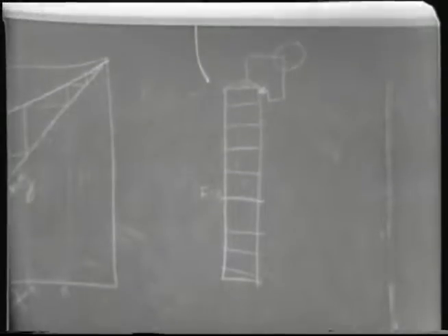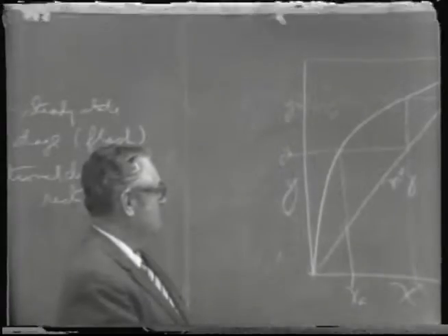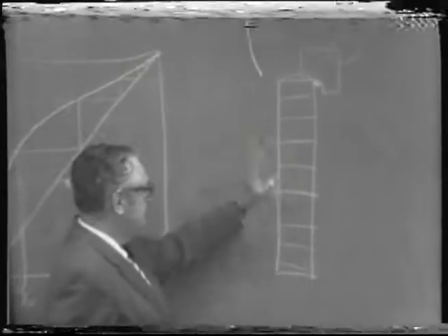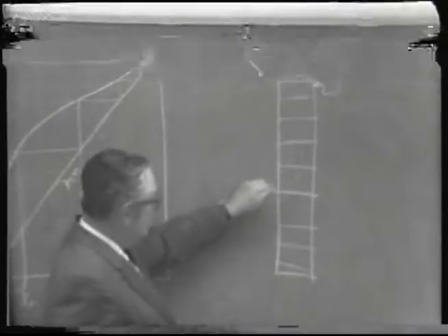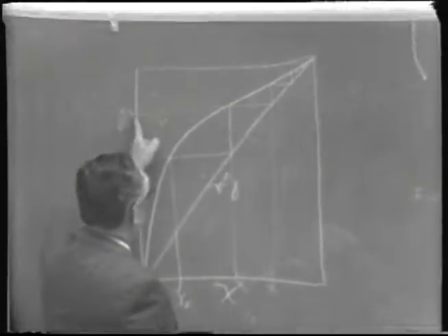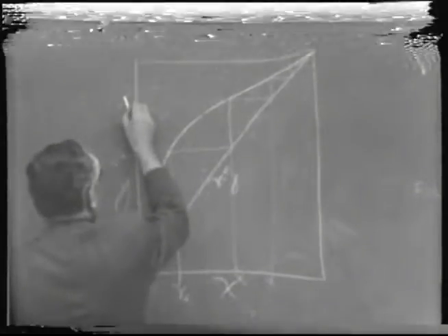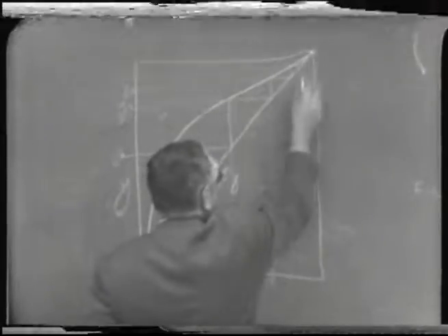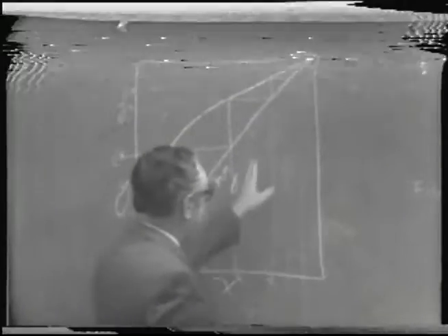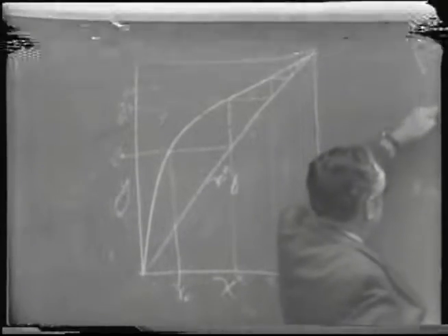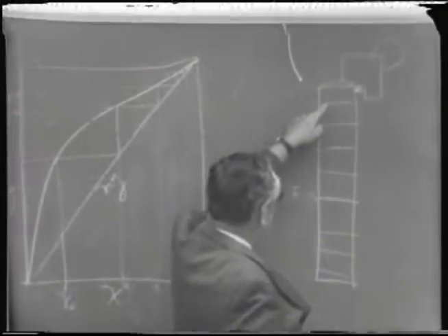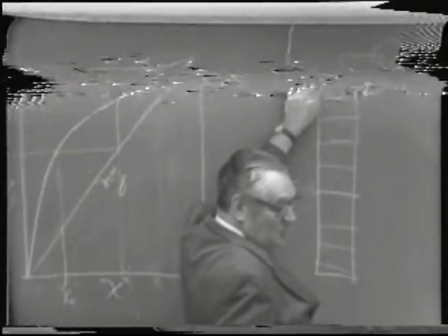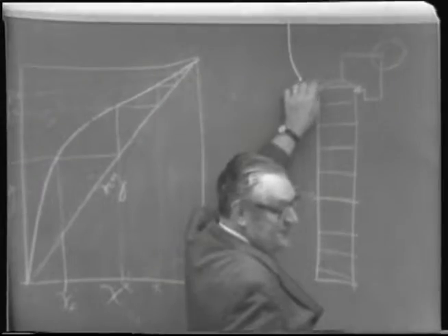In effect, we'd have this sort of situation, whereby if we took samples off each of these stages without disrupting the equilibrium, we'd find that they'd be represented by these values here, and so forth. Until, as we get a considerable number of stages, we'd find here toward the top that the change in concentration is small, because it's approaching the pure component.